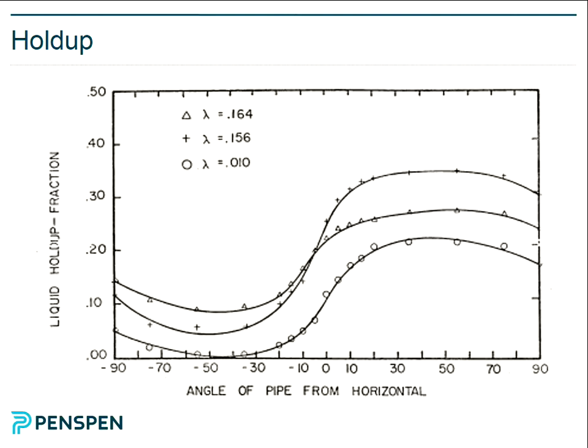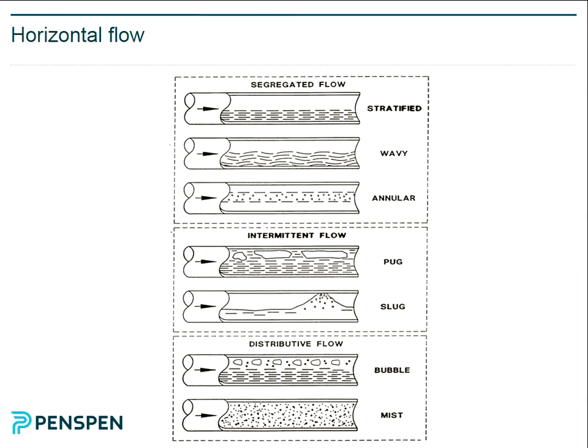So here there's not much difference between each part of the pipe. So we've got mist, small amount of liquid, large amount of gas, typically flowing at high velocities, like an aerosol almost. And bubbles the other way around. Basically, you've got small amounts of gas in liquid. So bubbles going to the top.